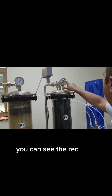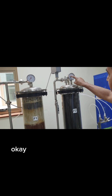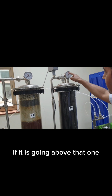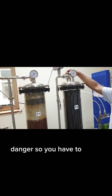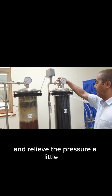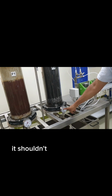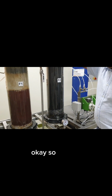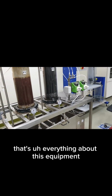If you can see the red sign here, the pressure shouldn't go above 10 bar. This is the maximum pressure it should attain. If it is going above that, it means the equipment is in danger. So you have to open a valve and release the pressure a little bit. Same for this one. It shouldn't go more than 10 bar. So that's everything about this equipment.